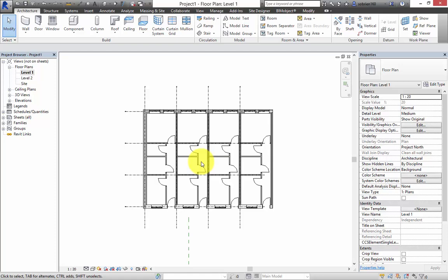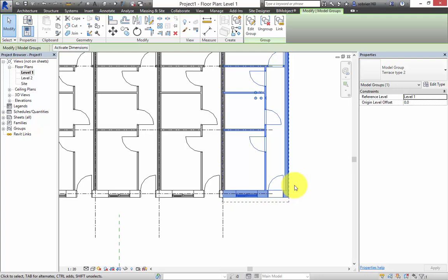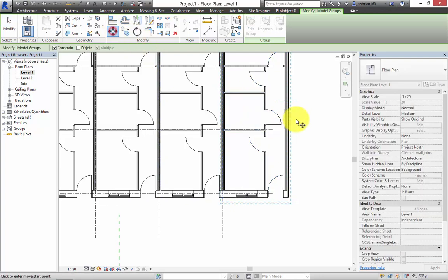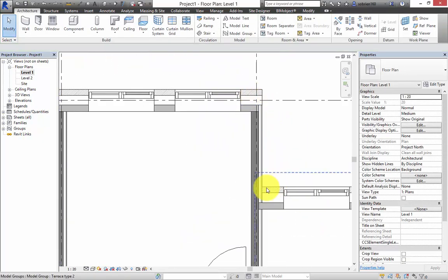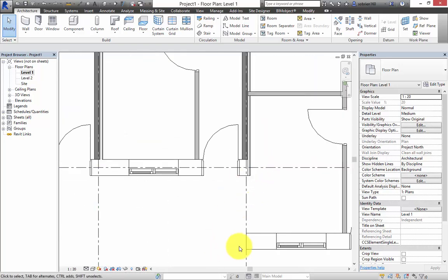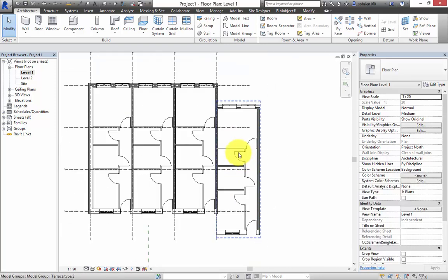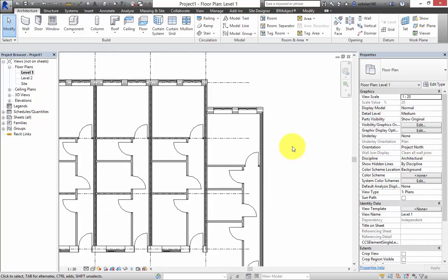It can be problematic, for example, if you want to stagger the houses. So let's say we wanted to move this house down 1800. You can see that straight away we have a problem here and we have a problem down here that we have to deal with in another kind of way. But we don't have that issue at the moment. If anybody has that issue, we have to deal with it on an individual basis because there isn't one overall method for dealing with it.